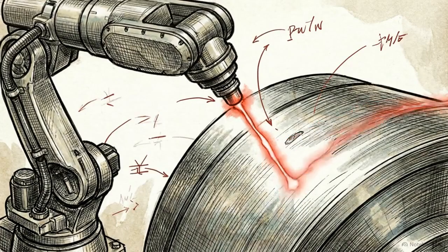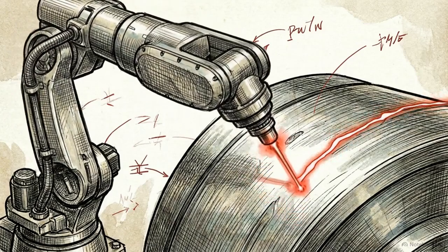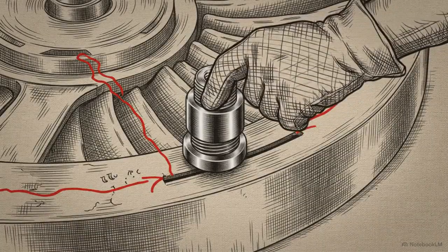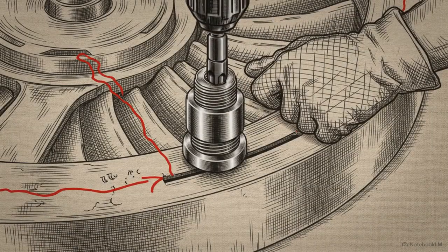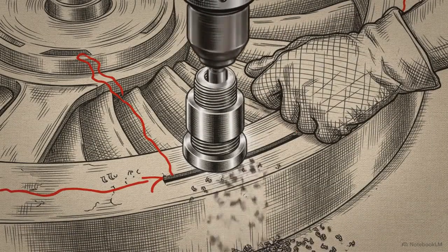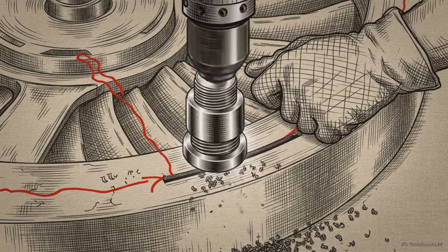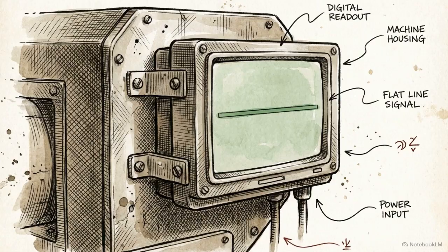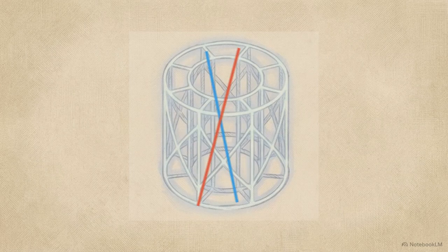Identifying the specific type of unbalance provides the exact coordinates needed to add or remove weight with precision. By adding engineered counterweights, technicians use mass to pull the principal inertia axis back toward the center until it merges with the rotational axis. Mechanical balance is more than just stopping a shake. It is the process of using physics to align